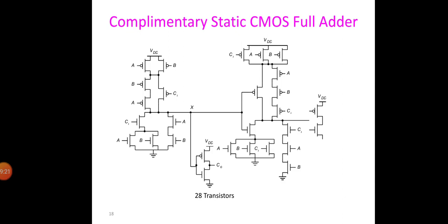Although slow, the circuit includes some smart design tricks. You can notice that the first stage of the carry generation circuit is designed with the Ci signal on the smaller PMOS stack, lowering its logical effort to 2. Also, the NMOS and PMOS transistors connected to Ci are placed as close as possible to the output of the gate. This is a direct application of a circuit optimization technique: the transistors on the critical path should be placed as close as possible to the output of the gate.